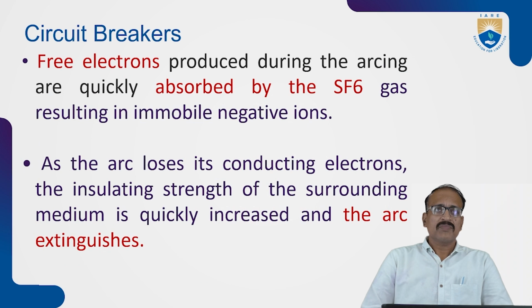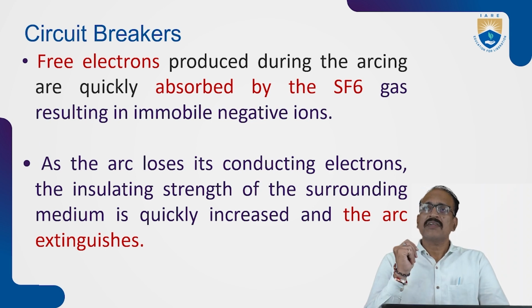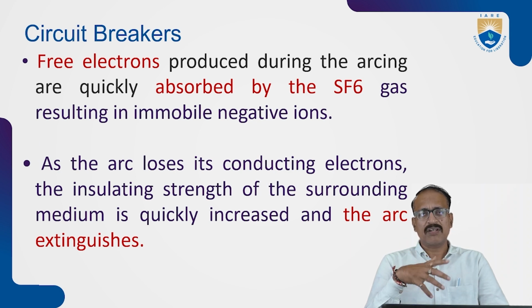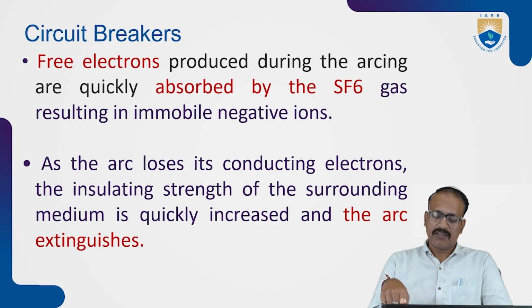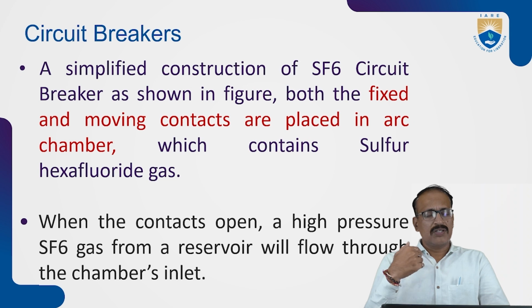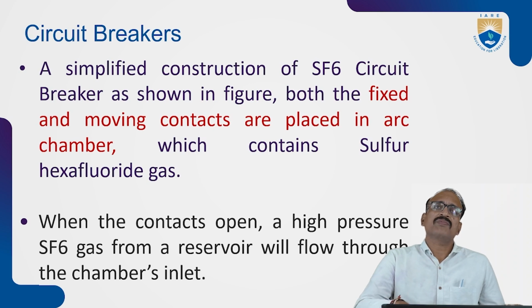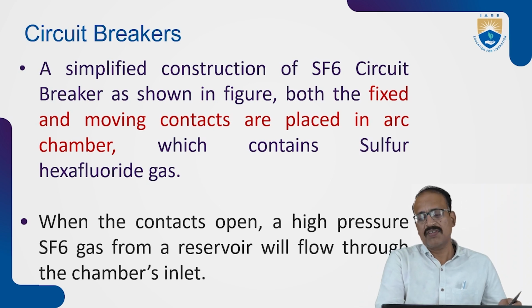Here the free electrons produced during the arcing are quickly absorbed, because it is electronegative in nature. Without electrons, the arc cannot conduct and cannot exist. That's why this is the specialty of SF6. It has almost the same construction as the remaining circuit breakers.